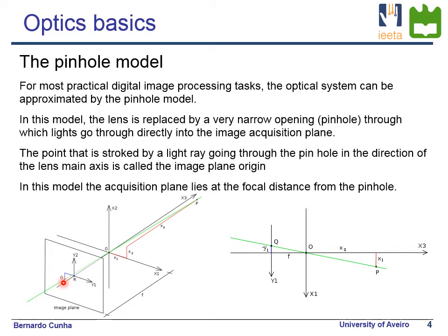And that is, of course, one of the limitations of a sensor that only has 2 dimensions, while our external world will actually have 3 dimensions. So by looking into this model, we can say that this pixel Q is equivalent to the projection of any point that lies along that green line. So we don't have any information of depth regarding the origin of this P source.